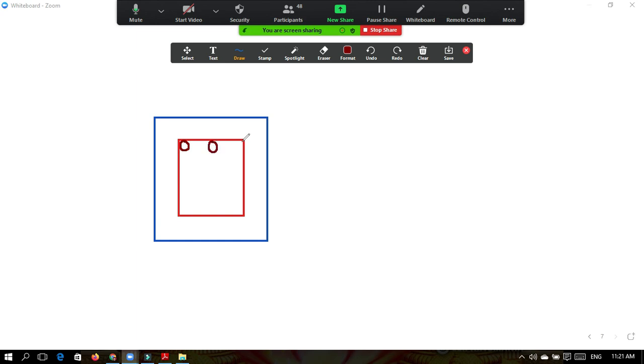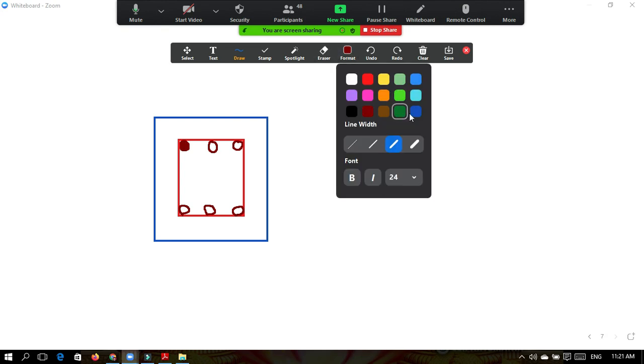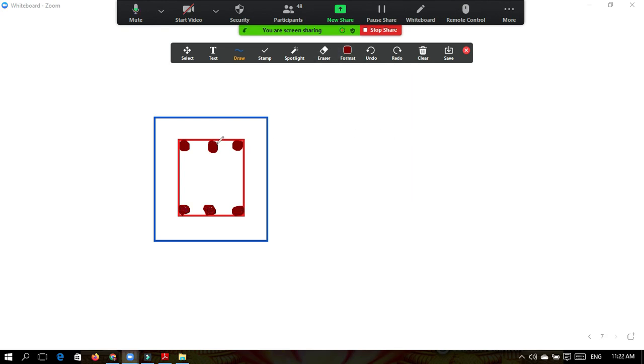At the top, 3 bars of 20 mm, and at bottom also 3 bars of 20 mm, and this is a 2-legged stirrup. So draw this reinforcement.